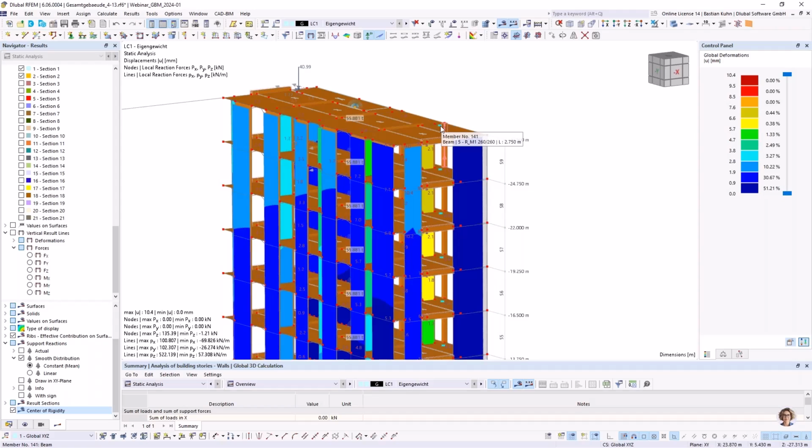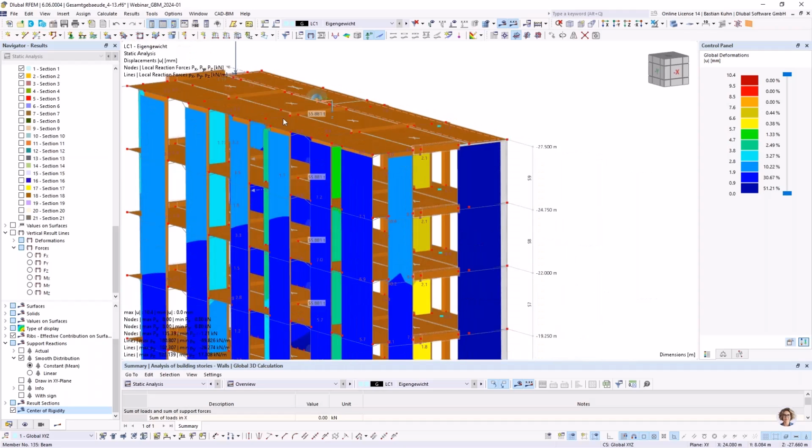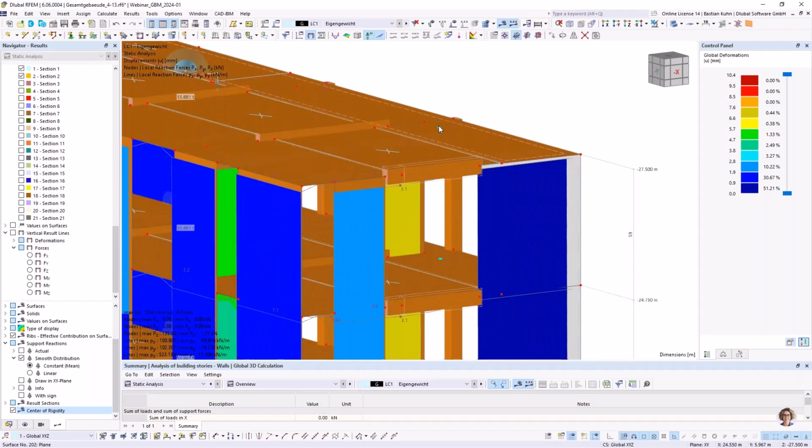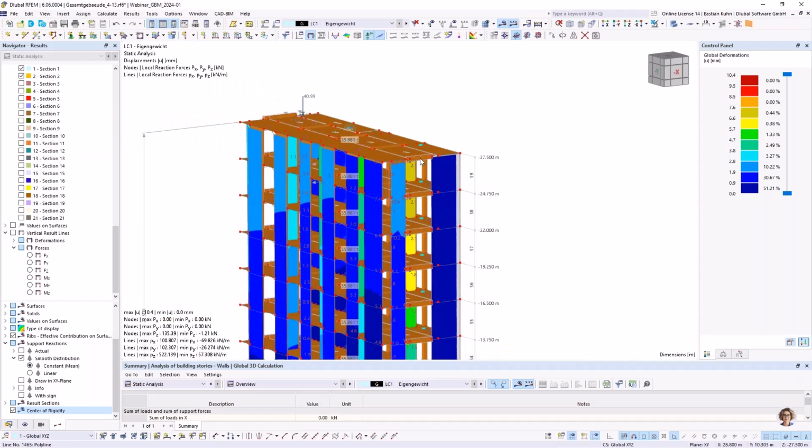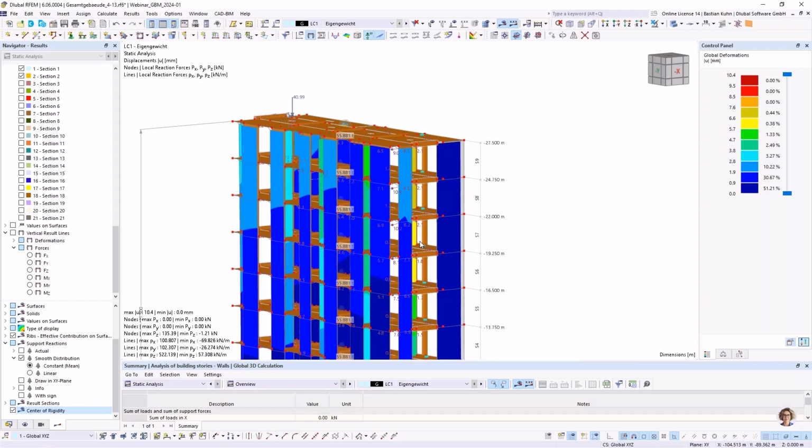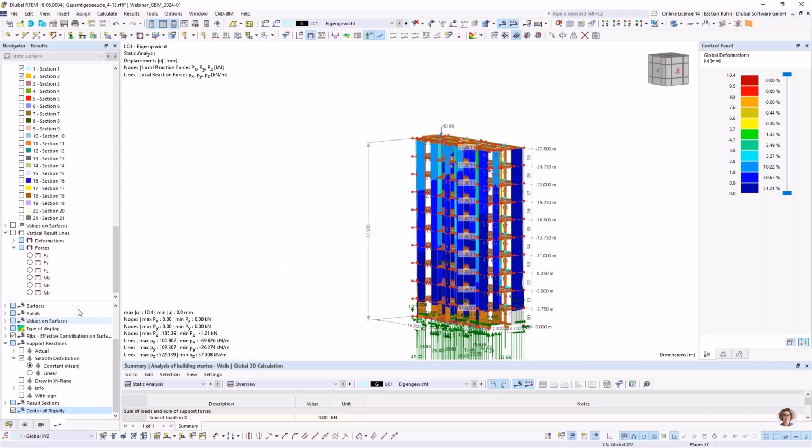And this is actually something when you are doing a dynamic analysis, which would also be possible with this add-on. It would regard your eigenvalue analysis due to the response spectrum method, and you would get the force in every story, and you could regard torsional effects by introducing load on the stiffness center, because if you introduce the load on this point via the eccentricity to the mass point, you can regard torsional behavior of the structure perfectly. In each story you have that, here, here, and here. Okay, this is one of the advantages of the building model.